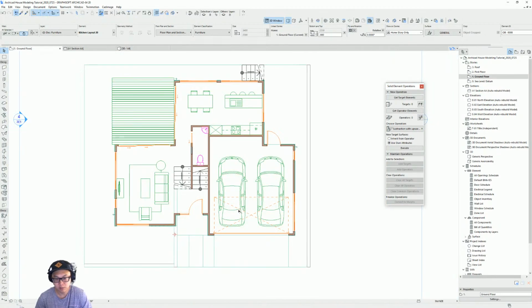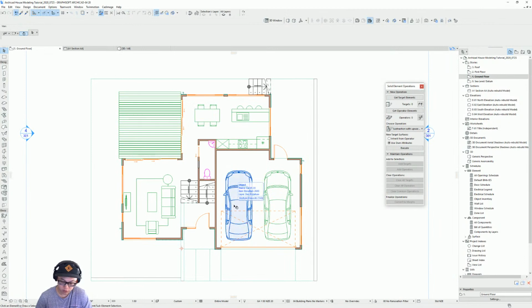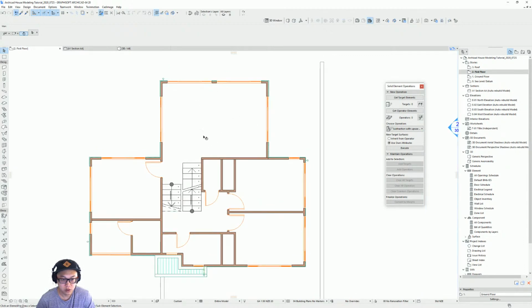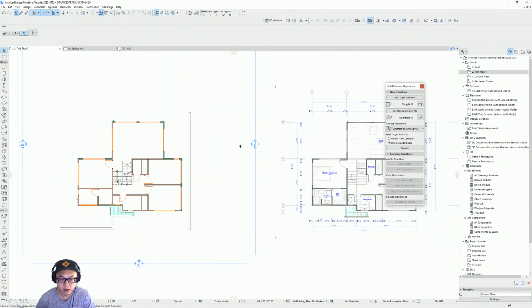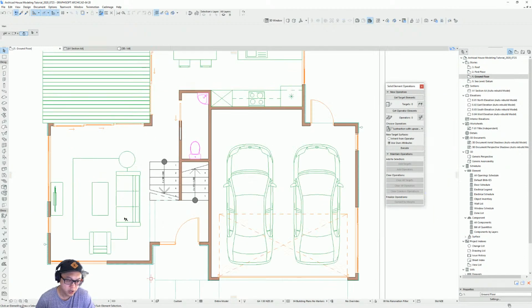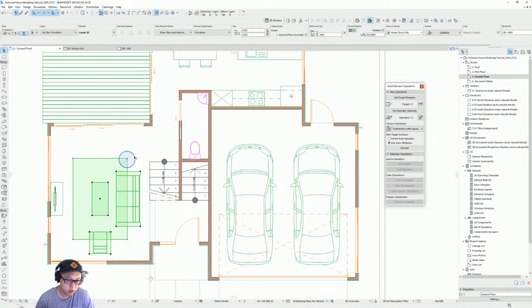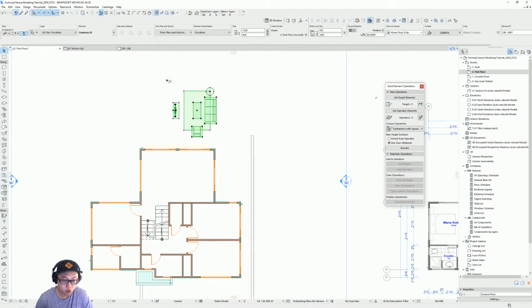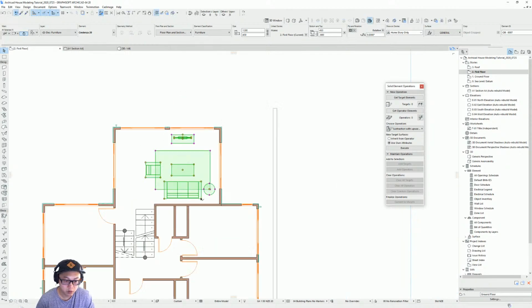We're just gonna go upstairs and put some beds. Control arrow up, and so yeah, not the living area. So actually, what I can do is take all those elements and copy, Control C, go back up, and Control V. And here, I select all those. I'm going to make a group of it by pressing Control J and then rotate them. And then we can put it into place.